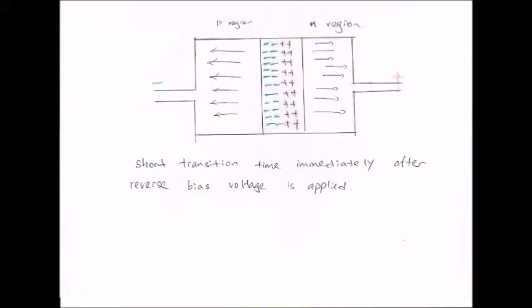When reverse bias voltage is applied, the positive side of the bias pulls the free electrons in the n region away from the p-n junction, causing additional positive ions to be created and widening the depletion region. In the p region, electrons from the negative side of the voltage source enter as valence electrons and move from hole to hole toward the depletion region, then create additional negative ions. As the depletion region widens, the availability of majority carriers decreases.